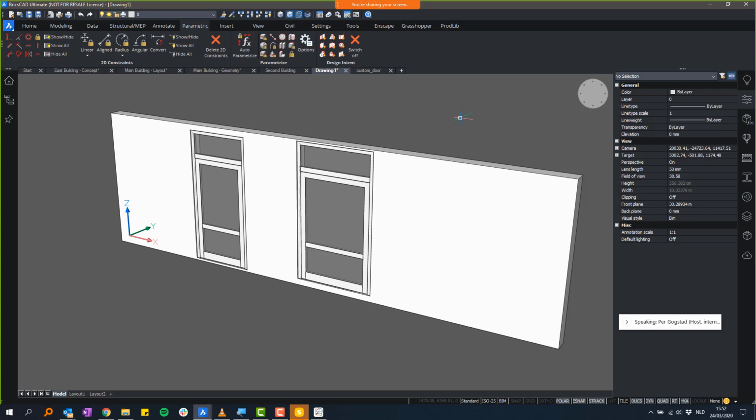So this way it's possible to bring in your own standards of RFA, but again, there's limitations. Well, actually, as far as I know, we're also improving the RFA import functionality, but we're dependent on the developments of the Open Design Alliance. So the ODA is reverse engineering the RFA and RVT file formats, and we're using that information to be able to import our own versions of RFA. So yeah, it's something we're working on, but it's limited.